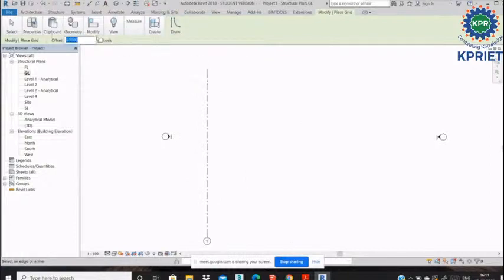Yeah, then the offset is there, right? Click the 3 meter offset, enter, right? Then go to the pick line, and automatically the line will be created 3 meters away. Now see, this to this is 3 meters.